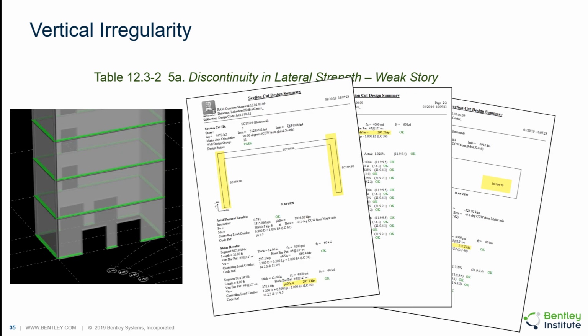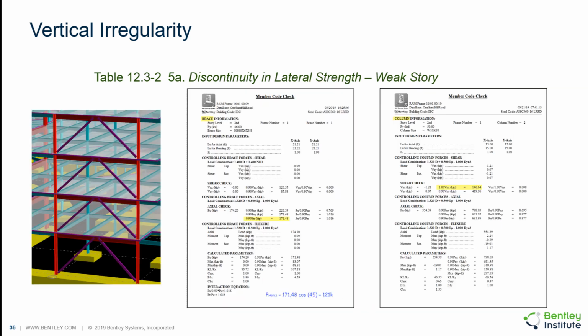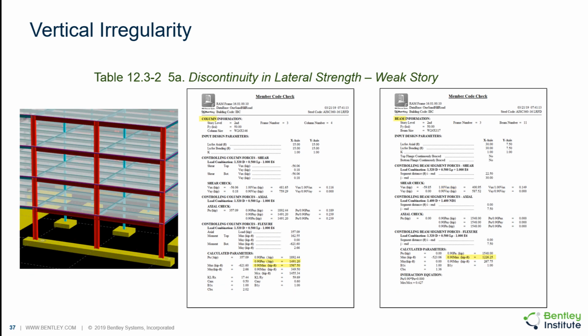For shear walls, sum up the shear capacities of the walls aligned with the direction of the seismic force. For brace frames, sum up the horizontal component of the brace axial strengths and the shear capacities of the columns. The code does not explicitly state that the strength intended for inclusion here is only the shear strength. In a moment frame, the column and beam flexural strength also resist the story shear.